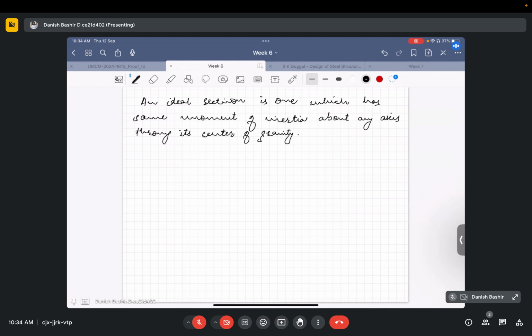Rolled steel sections cost less than built-up sections per unit weight. Rods and bars withstand very little compression when the length is more, we know that. Tubular sections are more suitable for small loads and lengths. These sections are usually provided for roof trusses and bracings.